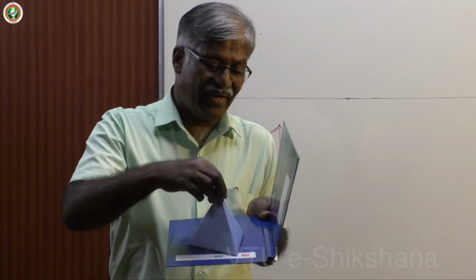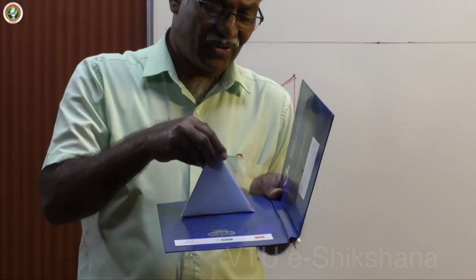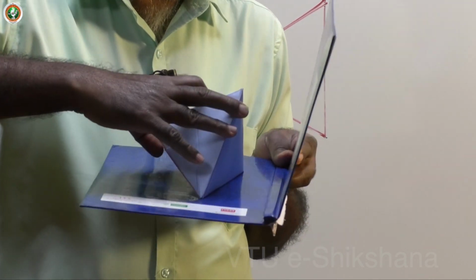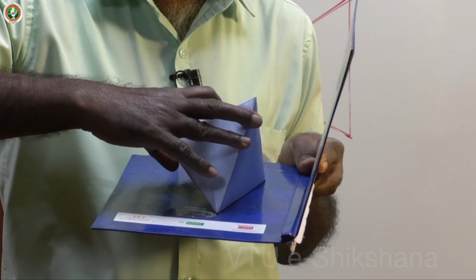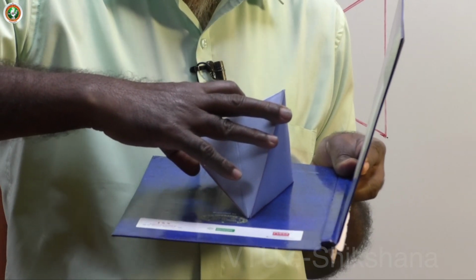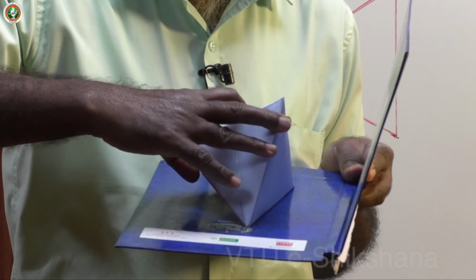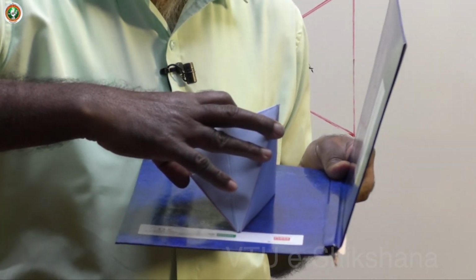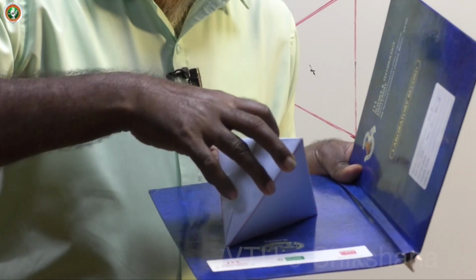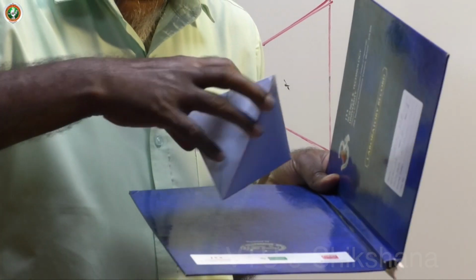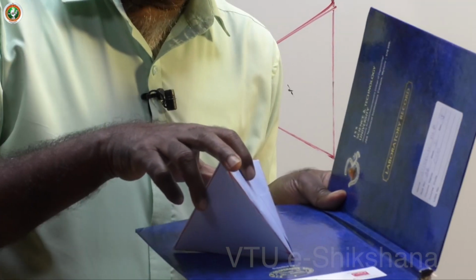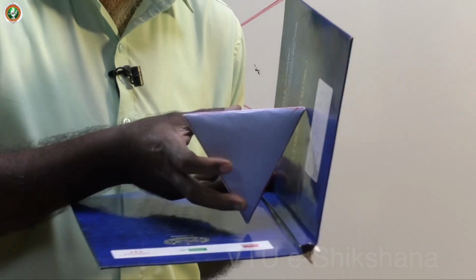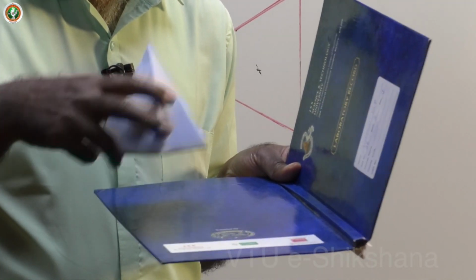Here, after giving the first position and second position, the side on HP will be turned 90 degrees. In front of means it is always parallel. So if no other information is given, always assume that the entire side is in front of VP by 20 mm. So this is VP; 20 mm in front of VP, draw a line and place it on this. That's all. One more position: it is inclined at 45 degrees to VP. This is case 1, this is case 2. You can take case 2 here also, but case 1 is fixed here, because at 20 mm you cannot accommodate the entire solid and take it away from it.